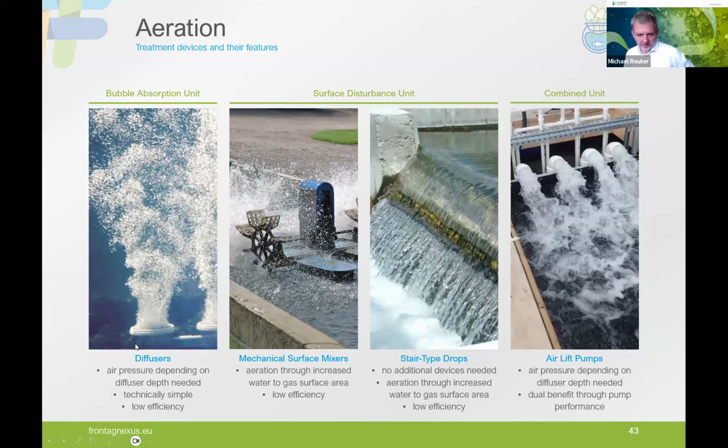As we use diffusers inside of the airlift pump to get the water lifted up, we will at the same time aerate the water with a diffuser, and also with a splashing inside of the culture unit. We will also aerate our fish tank while we transport the water inside. So these airlift pumps have kind of a dual benefit, as they gain head and aerate the system.